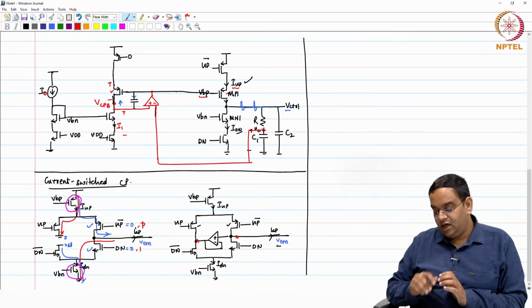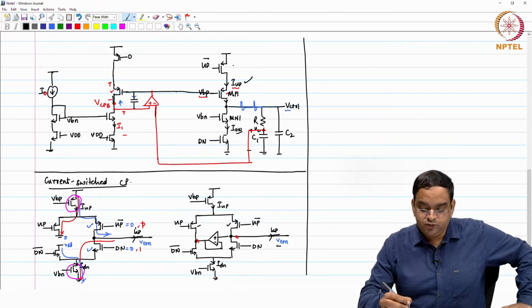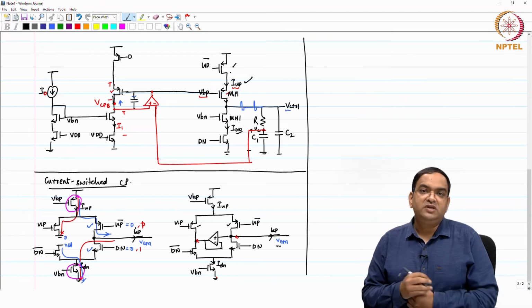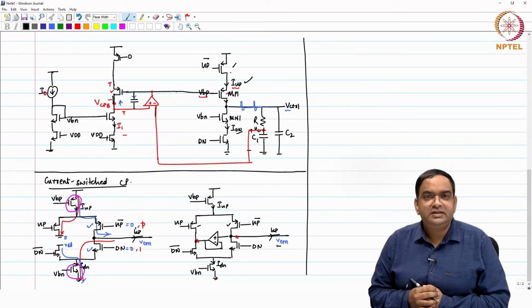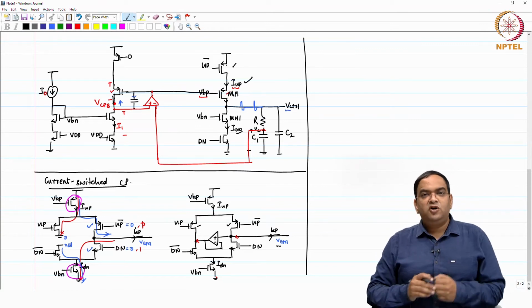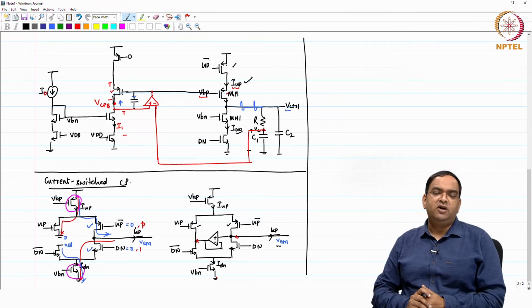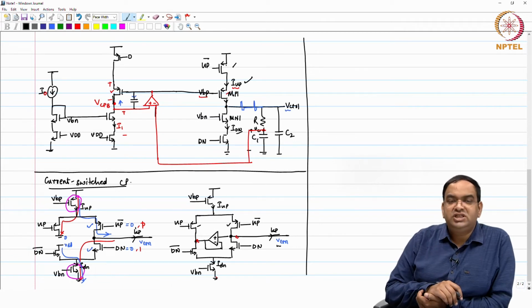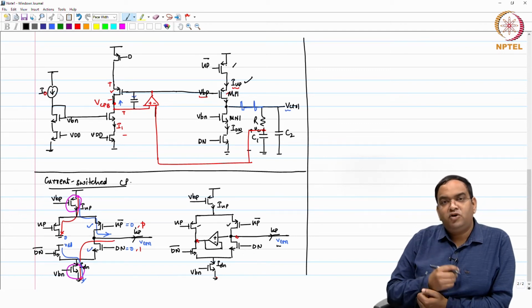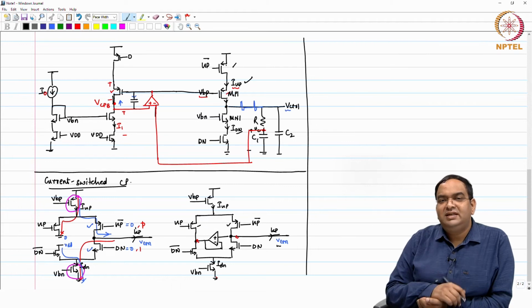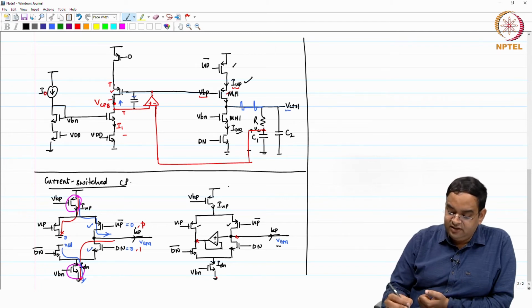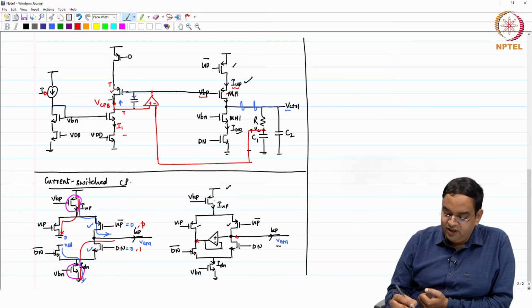Okay. Now, one important thing is that this particular source switched charge pump is consuming current only during the time when up and down pulses are high, and we know that in a steady state the charge pump is turned on only during the overlap period when you have up and down pulses both high. So, the current is consumed in the source switched charge pump only when you have the phase error or only during the overlap time, which is much lesser than the reference clock period. Okay.